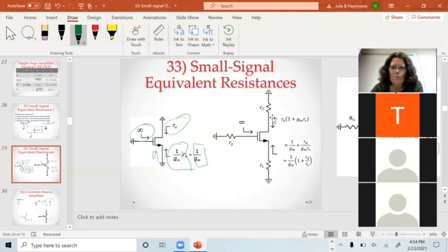Okay, so if I stick resistors in series with those contacts, and I look into the drain of the transistor, what I see is RO multiplied by this term, 1 plus GM times whatever resistance is hanging off the source. That could be a source resistor, it could be another transistor, it could be a lot of things. But looking into the drain of the transistor is pretty much the easiest way to figure out what resistance you see. Looking into the gate, you always see infinity.